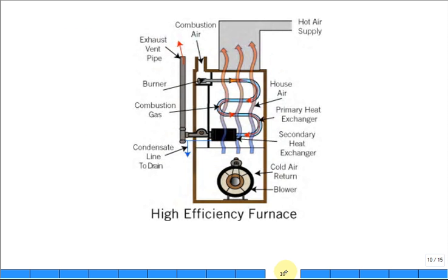So how do you get a high efficiency furnace? How do you get one that has this above 90% annual fuel utilization efficiency? You can't let the vent exhaust gases go out hot. And so if they can keep those below around 200 degrees F, then it's good. Okay? Well, what can happen is if you're burning some hydrocarbon fuel, that temperature can be below the dew point temperature of your exhaust. So what are you going to get? You're going to get a condensing furnace.